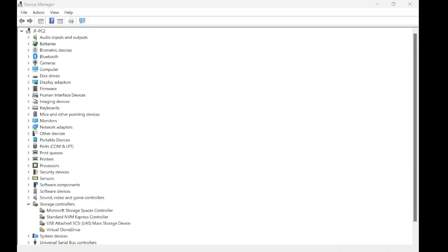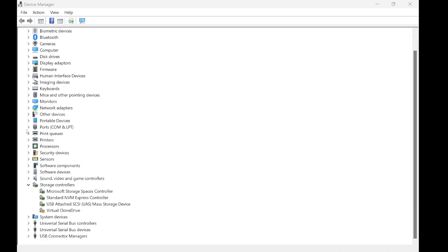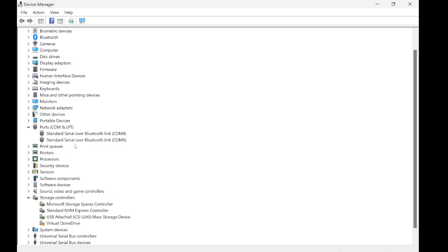Okay, so once you've connected the USB to serial converter to your computer, the next step is to figure out what COM port it is installed on. To find that out, you must open up Device Manager, then go to ports, and you'll see the two ports there.